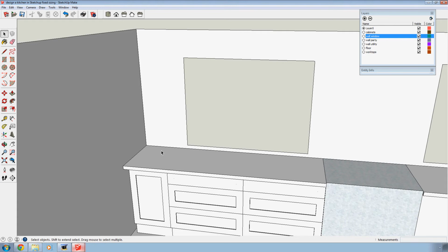And they might do a tall unit which would fit on there, but let's assume that they don't, and let's assume that we need to put in a wall unit, and let's assume it's going to be 400 because it'll definitely do a 400 size unit. So I'm going to get my rectangle key by pressing R, and if you look at the dimension box, you'll see that the width is the one that's shown first. So I'm going to enter 400, and let's say 720. That's certainly a standard wall unit size.